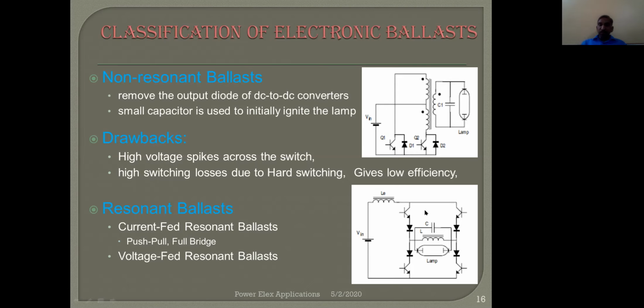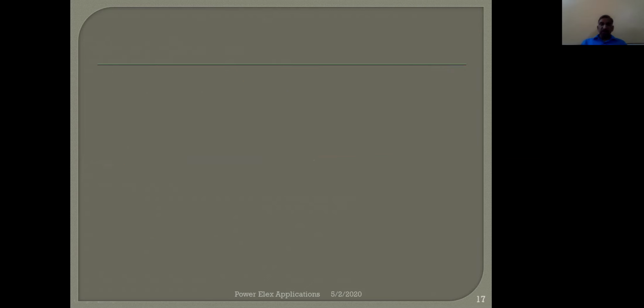This is a full bridge circuit where a transistor followed by a diode goes to this LC circuit, forming an H type of bridge, in order to resonate this LC tank circuit.